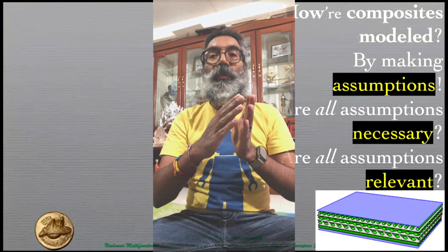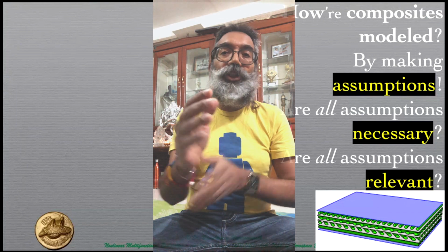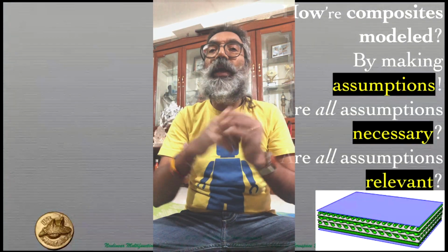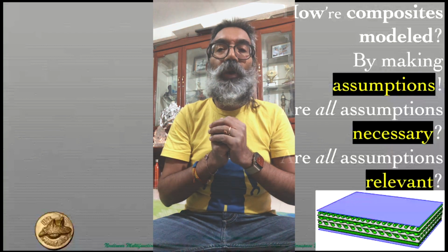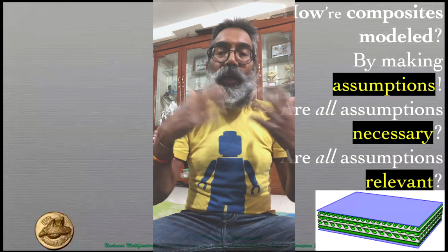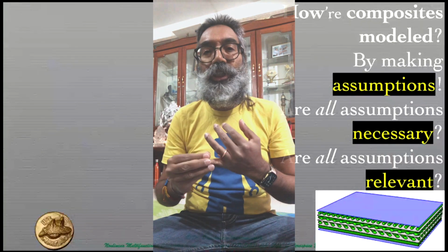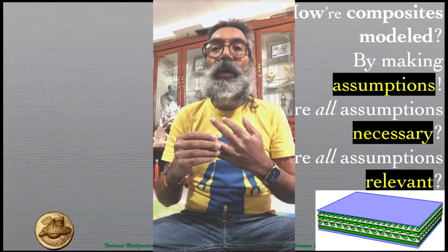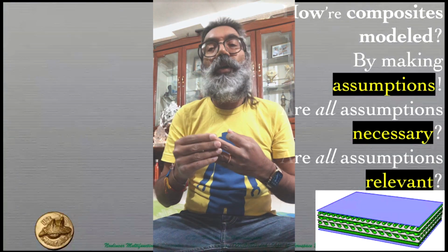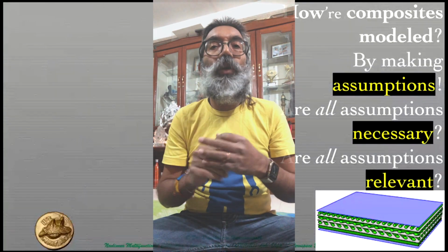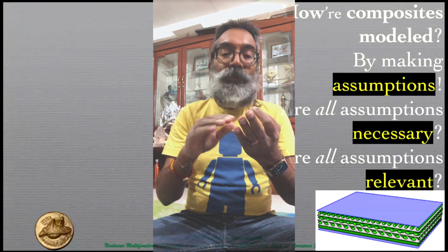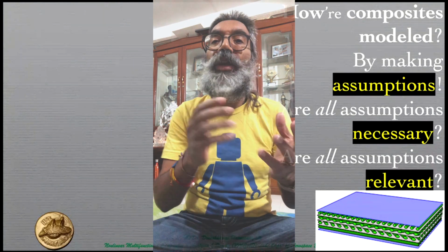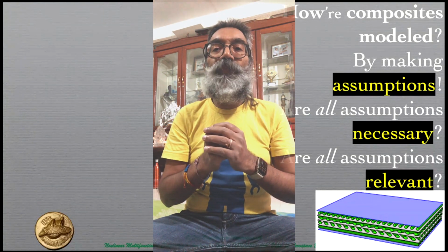So you're going from a beam-like 1D structure to a 2D structure, plate or shell, like a 3D structure, where all three spatial dimensions are important, and dynamics problems, which could involve vibrations, for example. It could involve fatigue, it could involve impact, which is an instantaneous load of large value that is applied. So in all these cases, you would have a time dependence coming in some way.